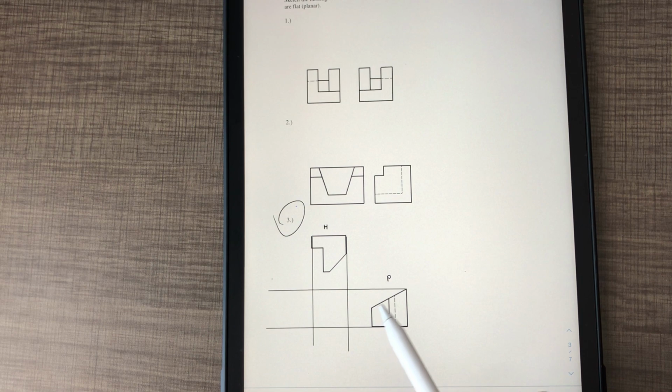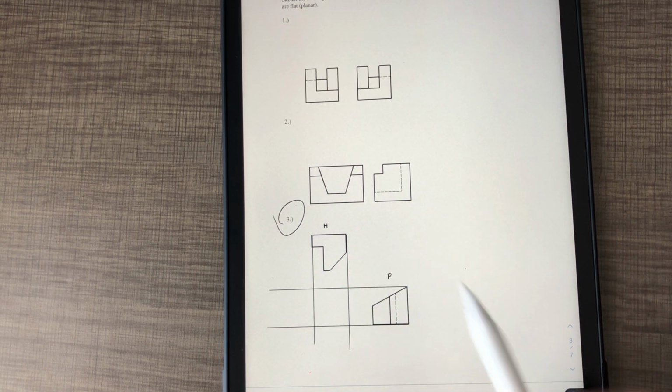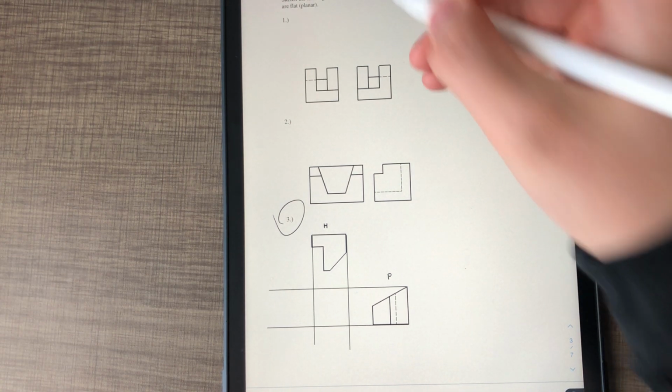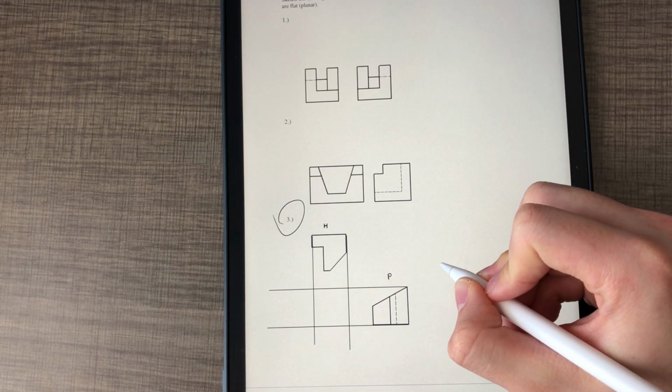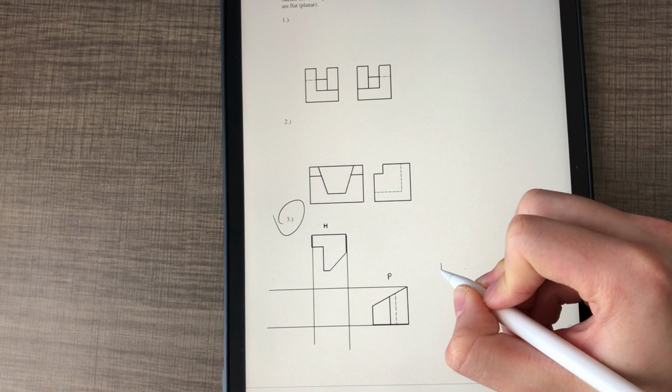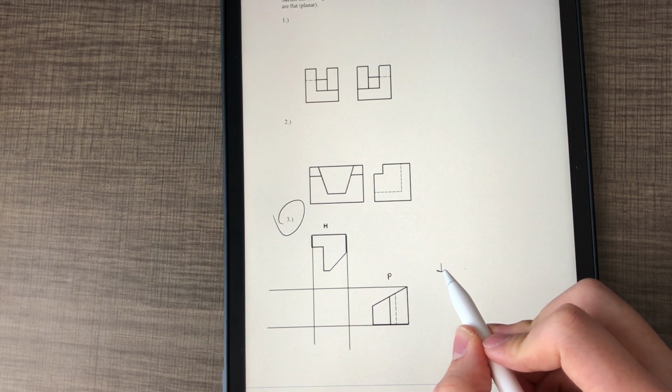The profile view is slanted, yet in the top view, all I see is this thing up here. I don't see any hidden lines. I don't see really anything. So how do I even approach a problem like this? Well, just like anything, let's start with a bounding box. So, of course, on the sketching assignment, we give you one of those nice little isometric cube things, but let's just draw kind of our own isometric. And let's get a bounding box.